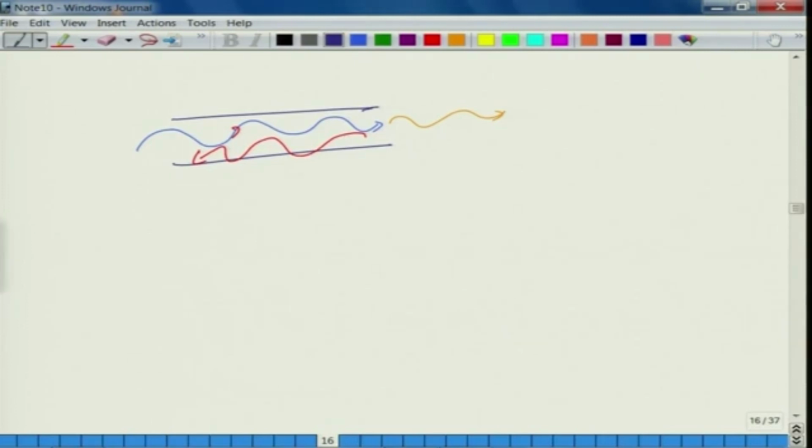So, just to keep it simple, I would just say this has been again subject matter of past research. Quite a few papers are there for acoustic radiation impedance seen at the end of an unflanged open pipe. Now we have this space also and this space also. It is no longer a half space. Half space means you have only infinite space in one direction, the other is constrained. You have almost a full spherical space minus this duct, of course.